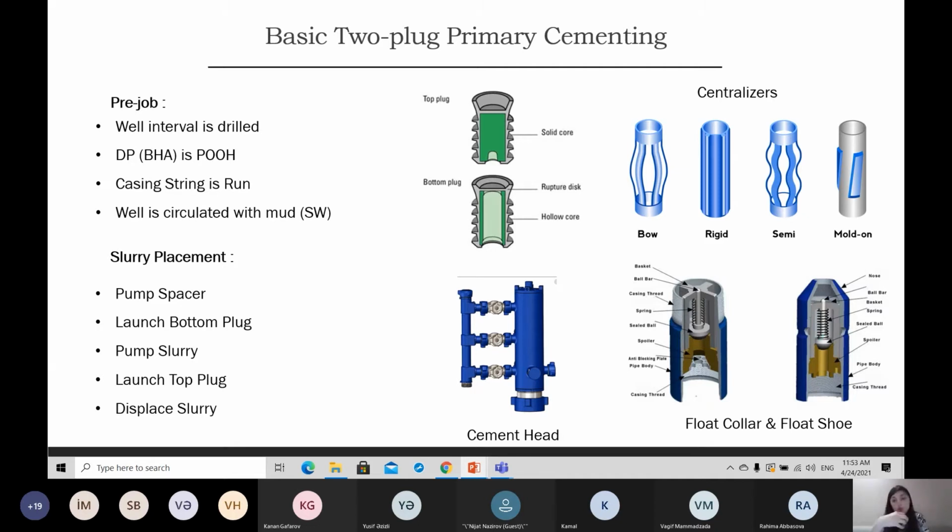So in each joint, in each 9 meters, we recommend using at least one centralizer per joint. Bow spring centralizers are good for open holes. Rigid centralizers can be used inside casing to casing, because the bow spring centralizers can enlarge, and when you have some narrow space, they can have a smaller diameter, okay? That's why they are good for open hole. When you have a washout, they have a maximum diameter and can extend, and they can give you better centralization.